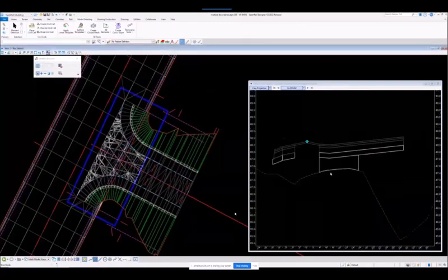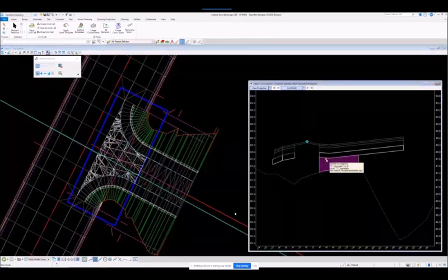As you can see, it creates in the three-dimensional model, and then obviously once I update my dynamic section, there it is. Obviously it has a volume. So you start thinking of what you could do with that. It's pretty powerful. Now I could pick, like I said, multiple meshes and fill that all the way across the bottom of that mainline corridor, and pick the top wearing course and the saddlebags on the cross, and just fill the whole thing in if I wanted to. But in this case, I just showed those single meshes, for both top and bottom.